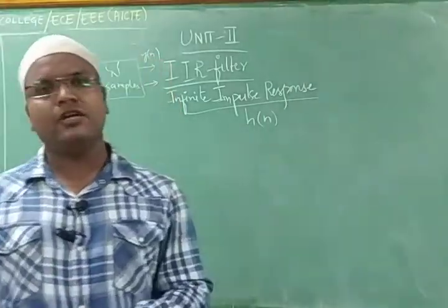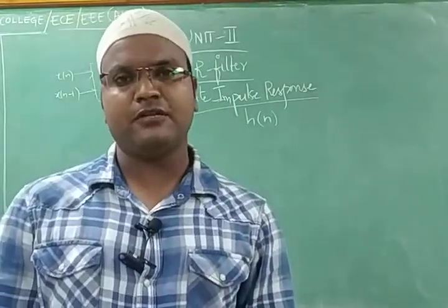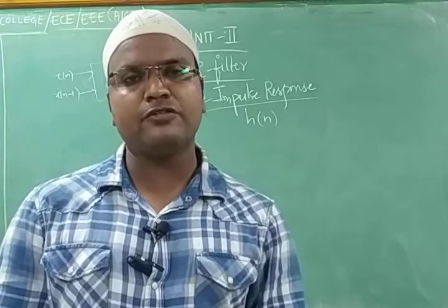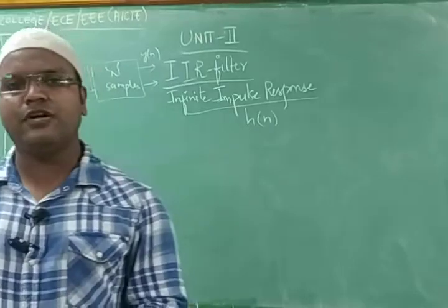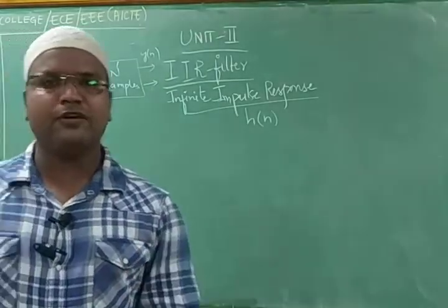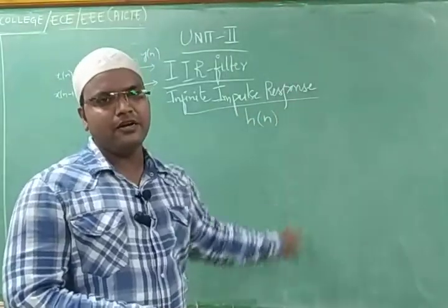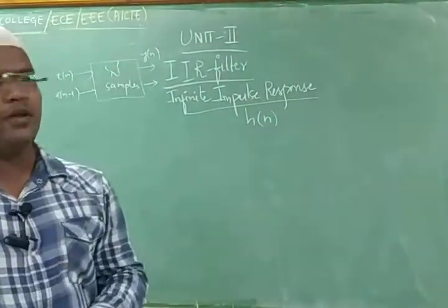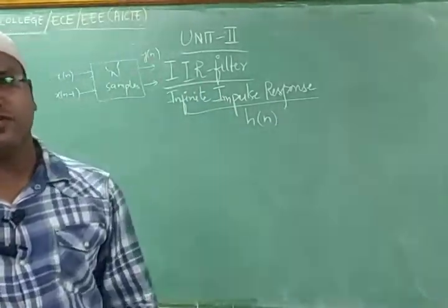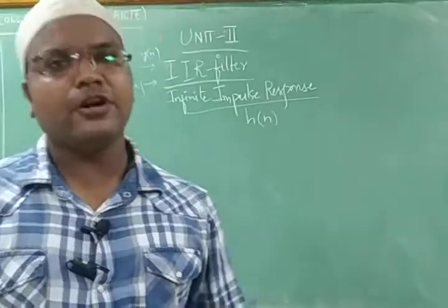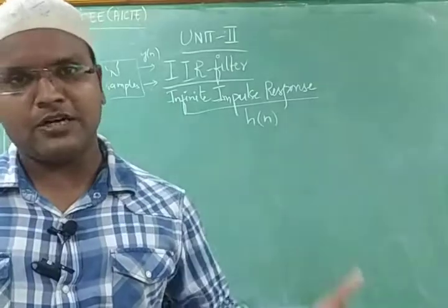What are the filters? We know them. We know about low pass filter, high pass, band stop filter, band pass filter. Band stop is one of the things which we are going to use, and one more name for that is band rejection filter. So by using all 4 types of filters, we are using infinite impulse response to find their particular output. For that we are applying this IIR filtering. In that, the first thing to keep in mind is that the IIR filter is recursive, so the output depends upon the present input and the past input, both values.